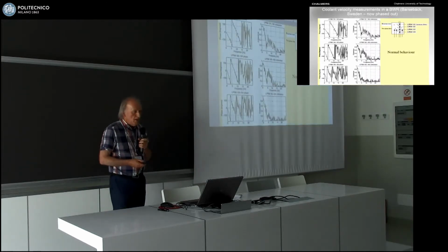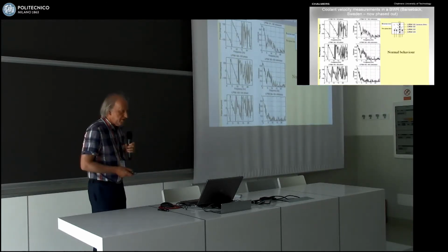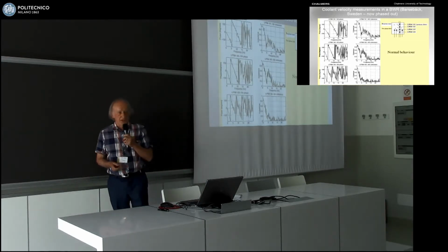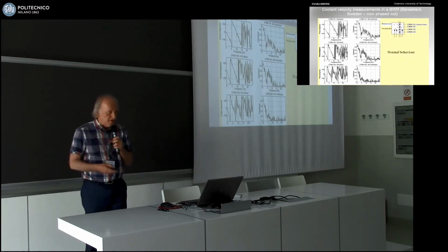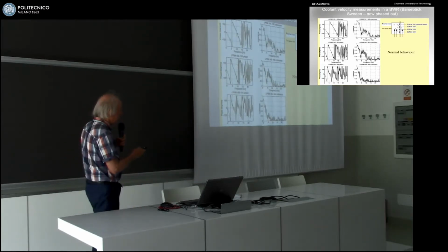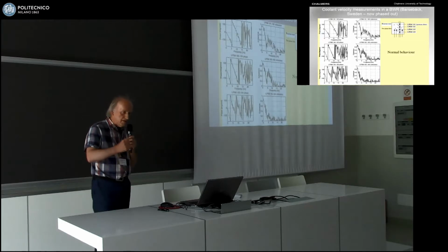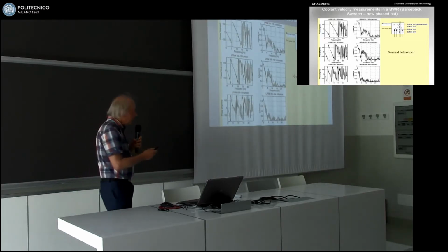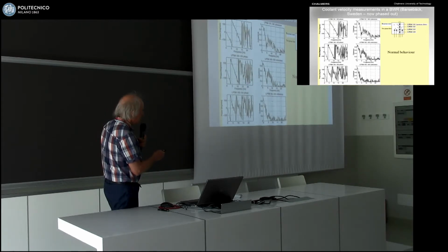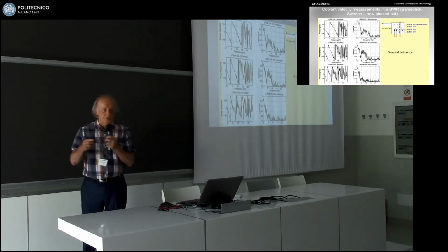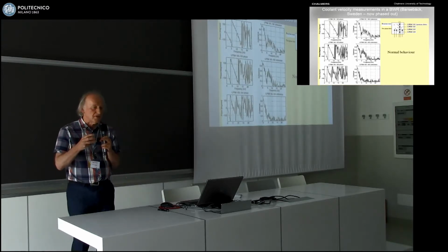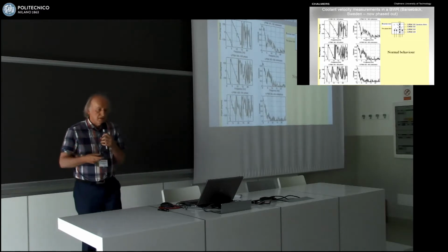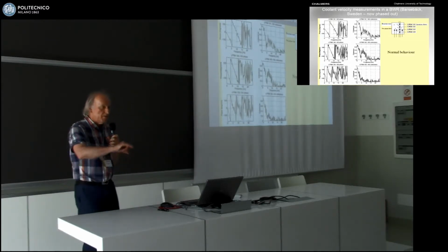So that's one case. As many of you probably know, it's also possible to measure the velocity of the two-phase flow in a boiling water reactor. I told you that there are 4 detectors axially in a detector string, and we have 36 detector strings. And if one takes neutron noise measurements in each detector and cross-correlates them, then one can find out the transit time, not the velocity, but the transit time, because you take just the cross-correlation function, and there will be a maximum at the transit time.